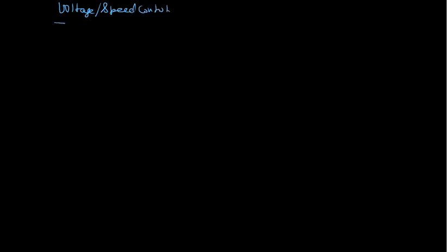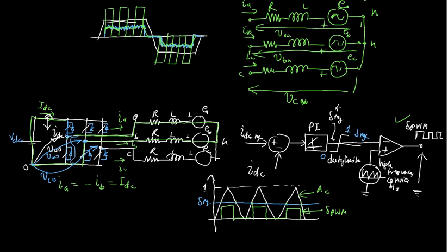Okay. So in speed control what we do is set a speed reference. There what we set? Current reference. And how are we getting the current? Please remember here that there is a relation between current and torque. You remember that the torque of this motor is 2K IDC. So the moment you set a torque reference, then you get a current reference. IDC reference is torque reference divided by 2K, where K is the back EMF constant. This is what it is.